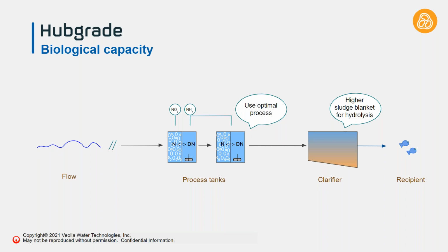By always monitoring what is going to be in the biological tanks, we know that what goes further down to the clarifier will always be within compliance and not over quality, not over aerating if ammonium is down towards zero. Then there's maybe a lot more value in starting a denitrification phase that would lower the nitrates, which would save you money and at the same time lower your overall TN concentration for the outlet.